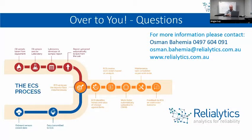So definitely patch test is a better way, because the analyst reviewing that patch will take that into consideration and give you a much more realistic picture of the oil cleanliness level. So yes, absolutely critical, but patch test is the method you would need to specify with the lab to get an accurate result.